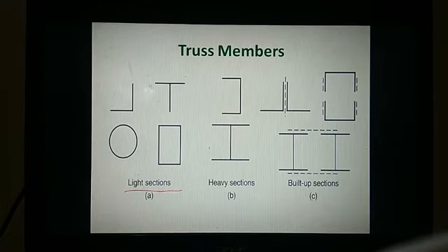Because people are going to ask you, in roof truss members, to make your structure economical even for light loads, which type of truss members can be used? Regularly, if you see canteens or even your college canteens, the truss members are made up of circular hollow members only. Why? Because it is more economical. At the same time, hollow circular members have more resistance towards torsion.